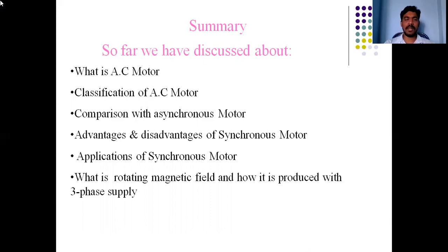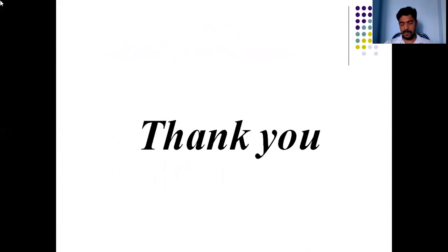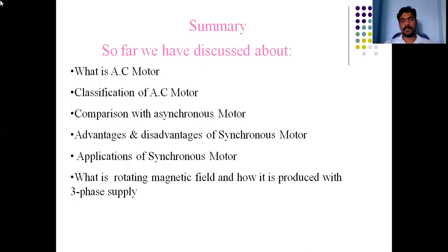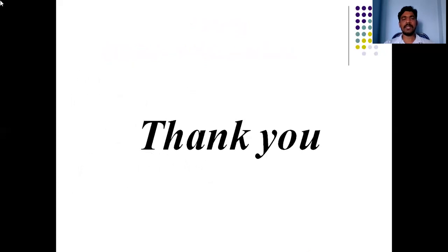And what is a rotating magnetic field? When we apply a balanced three-phase supply to the 120 degrees mechanically shifted winding, then the flux rotates at synchronous speed with a constant magnitude of 1.5 phi m. Constant magnitude, but rotating in nature, the field is produced.